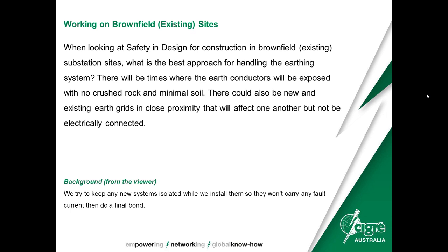they're the two outcomes. So typically it might be that you've decided on an exclusion zone and you are going to operate separated, so you'd install your grid, you'd do other various bits and pieces, but you might have to stay 10 metres away or 5 metres away or 2 metres away until you're ready to become the bird on the wire. And then, using safe work practices, those connections are made so that you're now part of the normal earth grid.